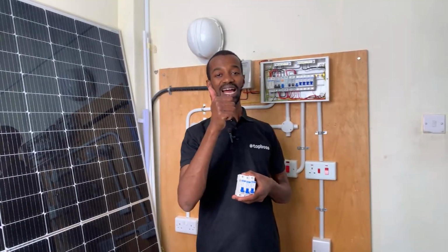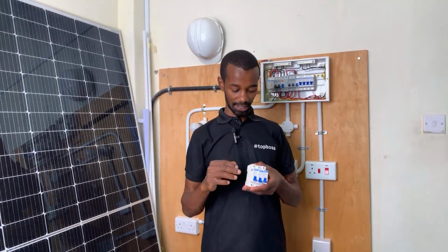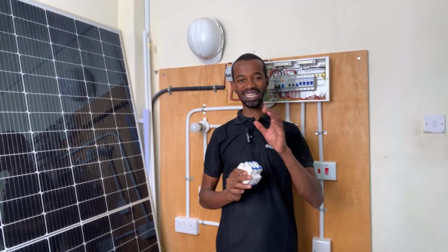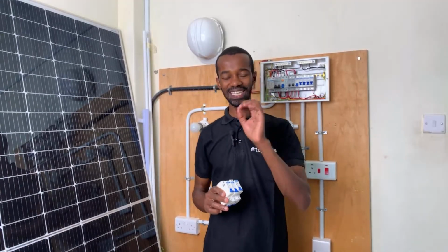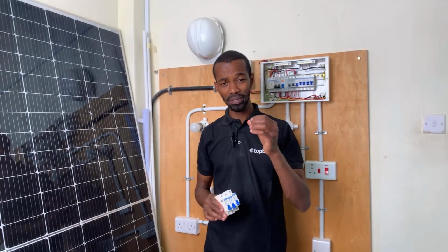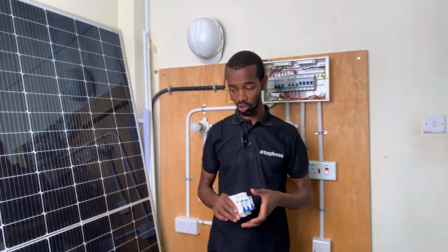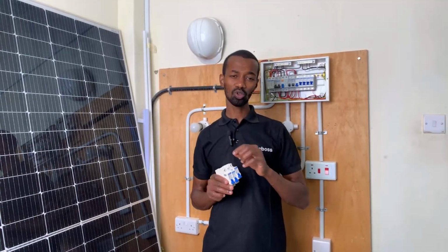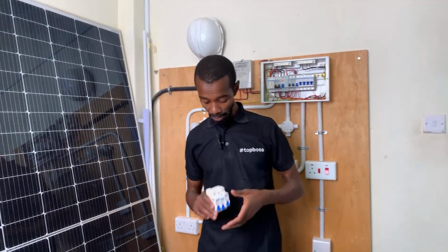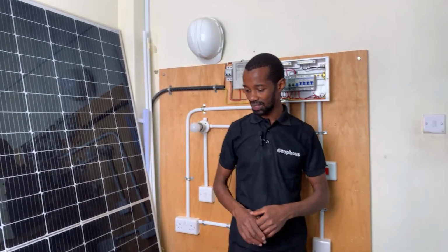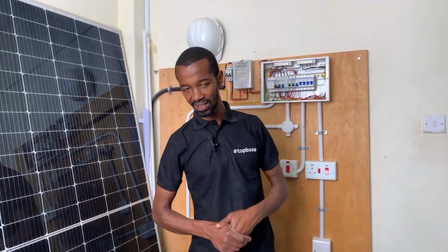Therefore, you need to connect a very low calibrated MCB so that in case there is any problem, in case there is an overcurrent, in case there is a short circuit, and remember, a short circuit will be of very little magnitude in this low powered circuit, therefore you are supposed to use a low rating MCB so that it can trip at the minimum load or at the minimum fault that occurs in that circuit. For instance, in this case, the lighting circuit.